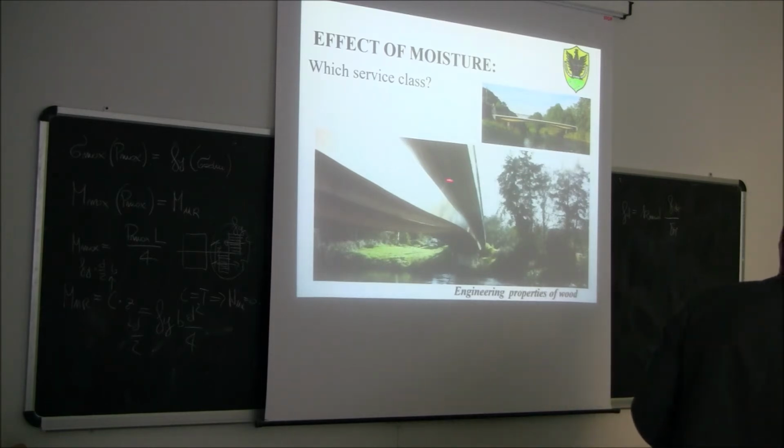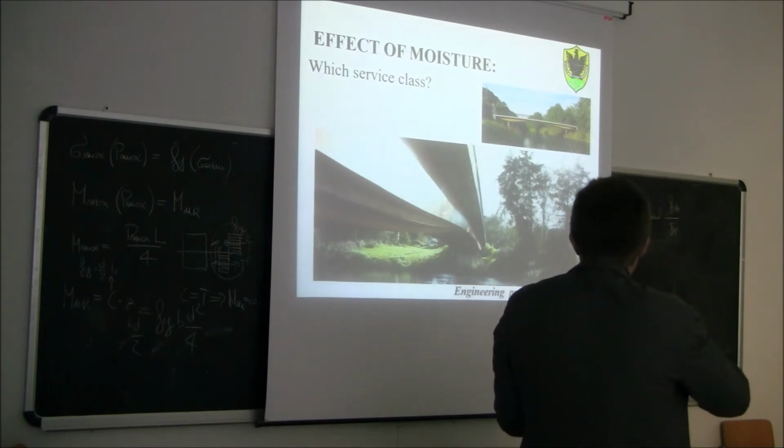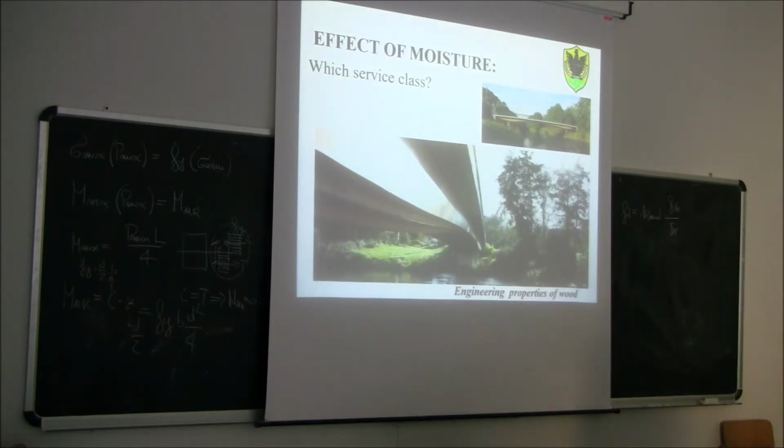But you see here, since there is this cantilever of concrete, in general, when it rains, this should be designed to have a depth such that the rain doesn't hit this part here. So this is not sure, it's somewhere in between. But in this case, since there is this cantilever, if there is a flow of air, you could also consider this as service class 2. Okay?